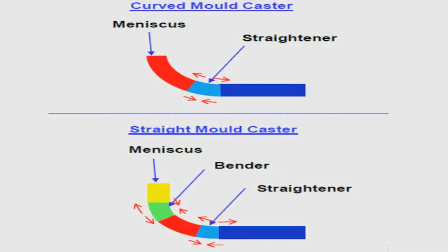Another important issue let me talk about: during continuous casting, there can be problems of entrapment at certain locations. I have mentioned earlier that continuous cast product does not have a uniform quality. Certain portions of the casting are relatively inferior in quality. I have mentioned that at the start of casting and the end of casting, at the changeover, at the stage of sudden fluctuation, there is a possibility of entrapment. So, those areas are relatively inferior.